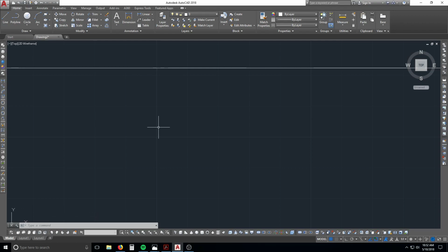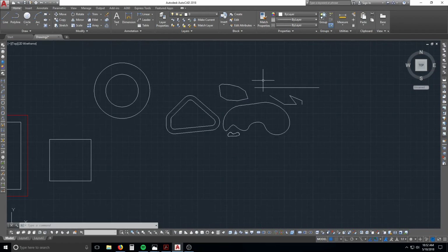Alright, this is something we haven't really talked about much yet. The next thing is your layer. Your layers are an incredibly important part of AutoCAD, and that's right here. You can access your layers here or by typing in LA. But to change on the fly, you're just going to go here. And these three are in here because I inserted that block in the very beginning of our tutorial, and these three layers were in this block. So the system remembers those layers.